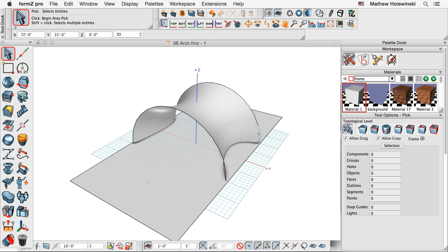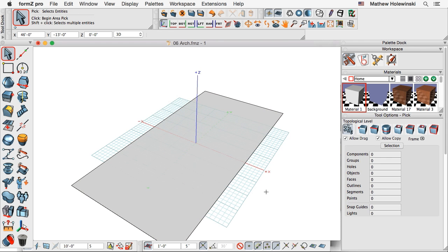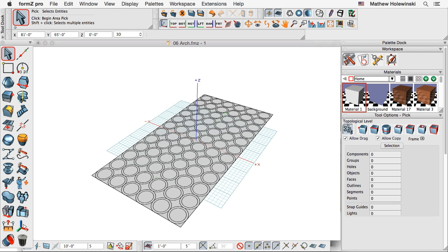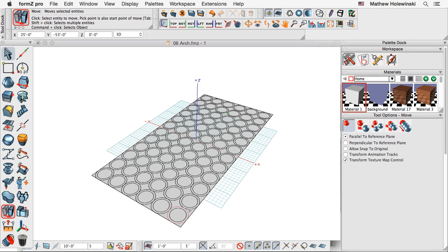We're going to create a 2D rectangle. And for the rectangle, you could match the overall size of the unfolded surface if you want, or in this case, I just drew an approximate shape of the actual size there. And I created a series of circles. These are separate circles. So you can see if I were to move these off to the side, I created one circle, and then I did a move multi-copy and just copied a whole bunch on there.